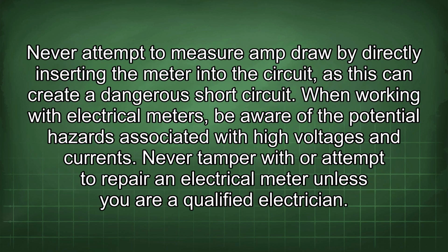Never attempt to measure amp draw by directly inserting the meter into the circuit, as this can create a dangerous short circuit. When working with electrical meters, be aware of the potential hazards associated with high voltages and currents. Never tamper with or attempt to repair an electrical meter unless you are a qualified electrician.